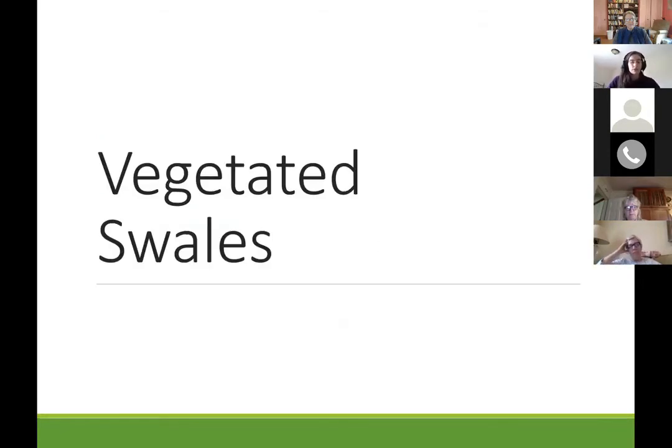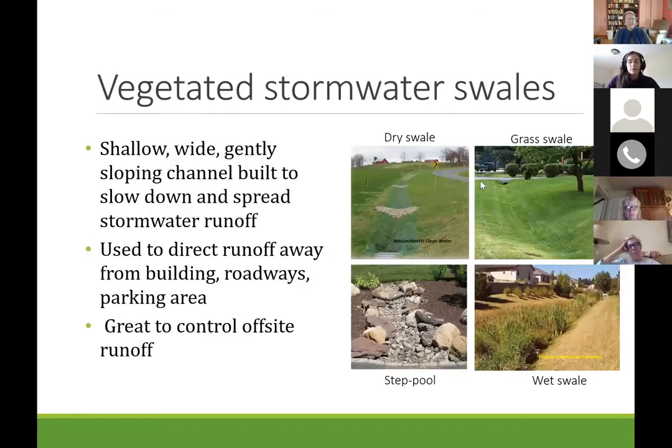Next, we're going to discuss vegetated swales. One of the homeowner associations that I received pictures from was actually referring to issues with swales, and we'll get to those photos later. But generally, swales are these channels built to convey runoff. You want them to be well stabilized, so you do want to have vegetation there, or even, if it's too steep, you might have to use rock material because the vegetation might not be able to handle the steep slope and slow that water down adequately.